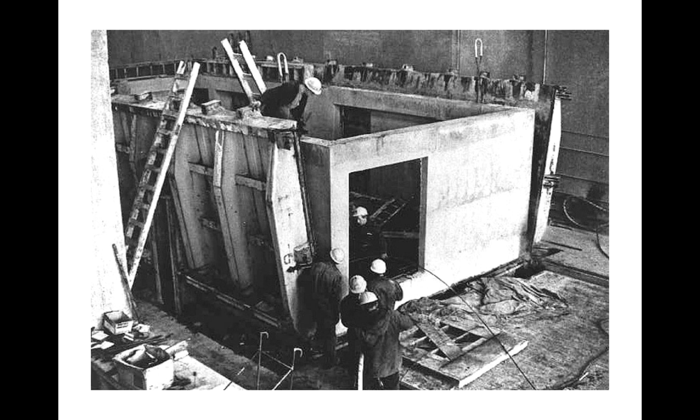And you can't see it here, but there are also channels that are cast for all of the post-tensioning cables that the Commandant specified. Even though this is a concrete job site, because it's in factory conditions, they can control the temperature, they can control the humidity, they never have snow days, they never have rain days. So you're able to keep to a schedule, and you're also able to ensure a much higher level of quality and a much higher level of precision than if you were casting all of this concrete on site.